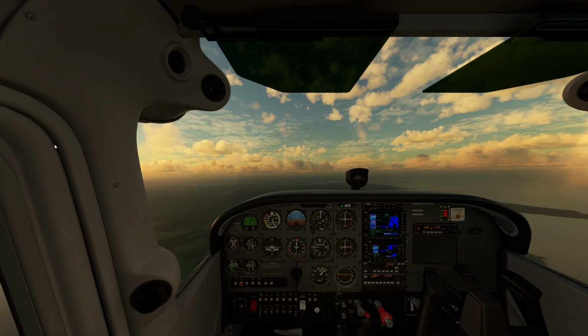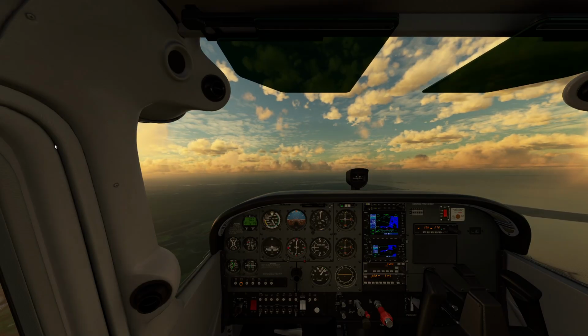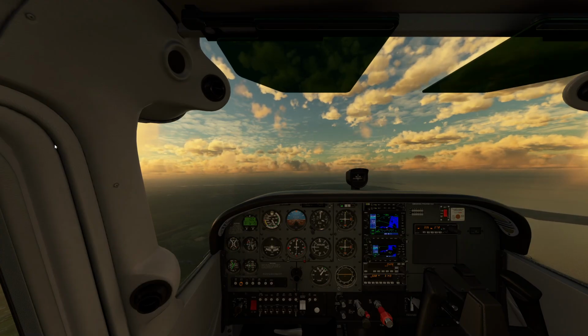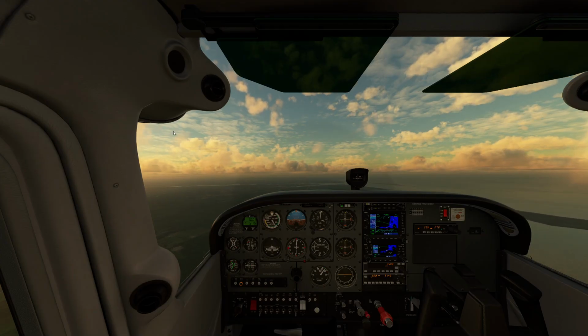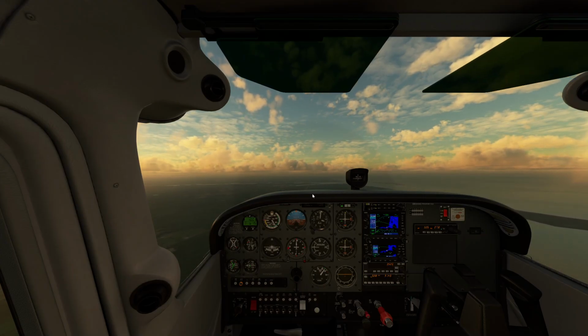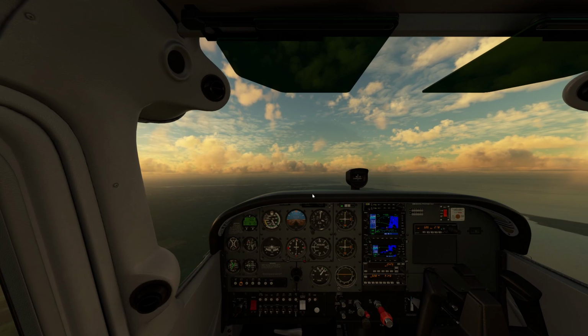Alright, so we're almost up to 1 Charlie there. Some basic things that we have to know, just kind of this lesson knowledge. What we want to do is check the aircraft attitude relative to the horizon. It's kind of hard to simulate in the simulator, but what you would actually do is hold out your hand in front of you, and you'd want to see about 4 fingers worth between the cowling or the dash of your airplane and where the horizon is.